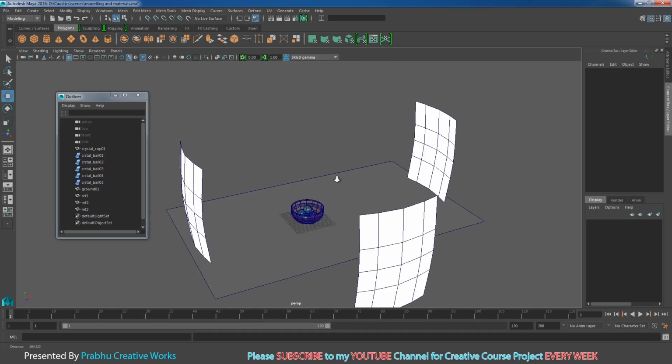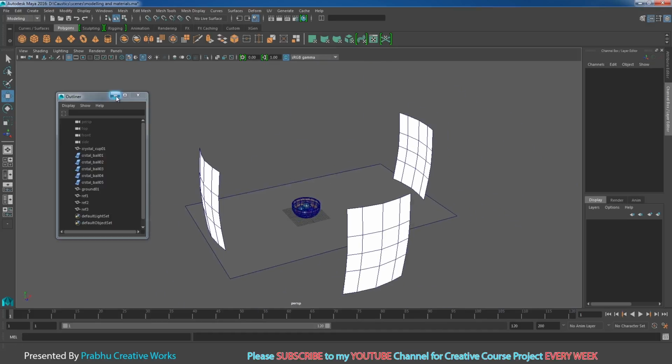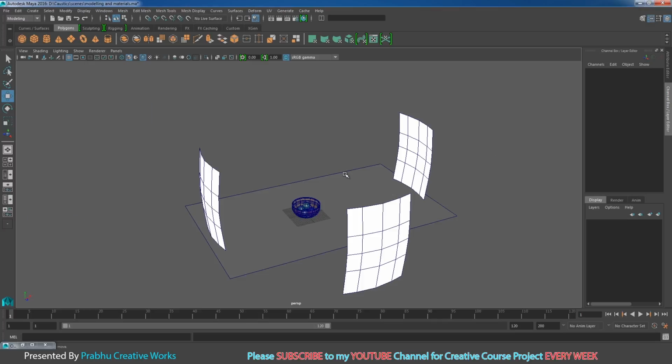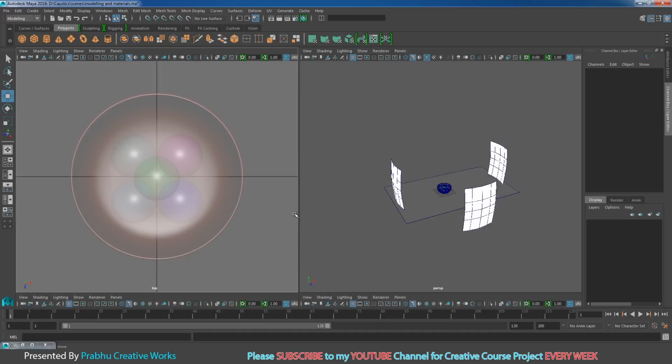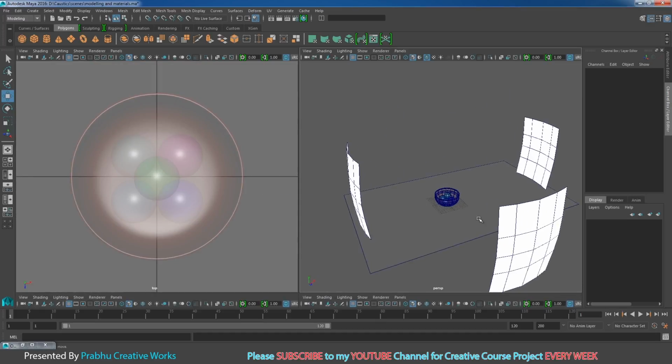Before we set the light, you want to set the camera view. I will click spacebar to switch over my 4 views. I will extend this one, so that means you get only 2 views. Here we want the perspective view. Here I want to set this as a camera view. So go to rendering, click on create camera.